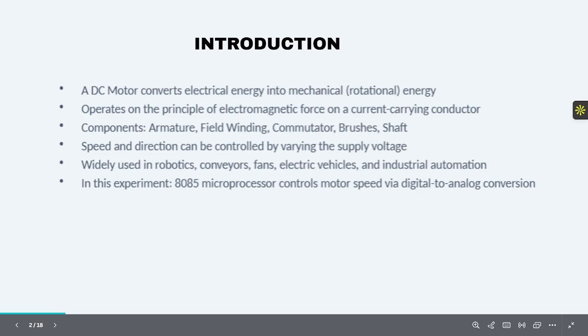and ease of control. However, one major problem with DC motors is that when they start suddenly, a high current flows through the circuit, which can damage the motor and reduce its life. Similarly, sudden stopping of the motor can cause mechanical stress or jerks. To overcome these issues, we use the concept of soft start and soft stop.